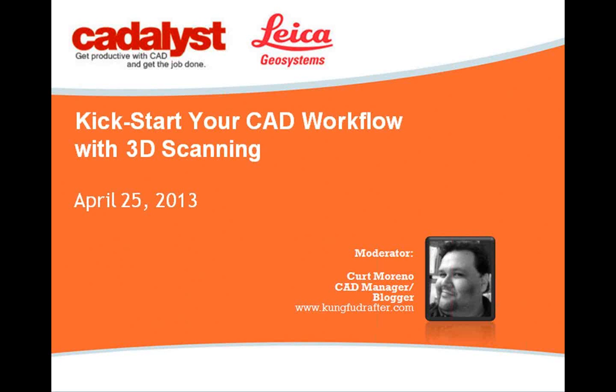So let's get started by tackling some of the basics. And these are going to be very basic for you, but I know that I'll find them enlightening. What is 3D laser scanning, and how does it relate to CAD workflow? Well, that's a good question. Laser scanning has been around for longer than terrestrial laser scanning, and that's a better way to put it. These stationary terrestrial laser scanners collect millions of 3D coordinates many times per second, up to a range of about 300 meters, forming what we call a point cloud.